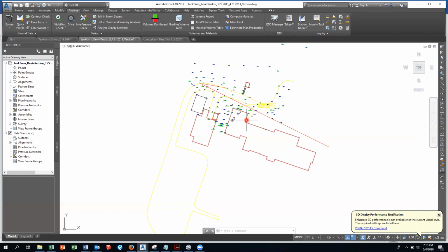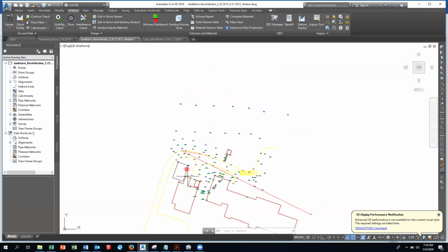We're going to try to do a little bit of road layout on that project, a little route surveying. On the old design at the steam plant, they have what's known as point of intersection and point of tangency, and they give coordinates, northing and easting, for that. So we're going to be able to lay out the road, which extended out. If the tank farm's out in here, this roadway extended out to the pump house. So we'll get into a little bit of route surveying.